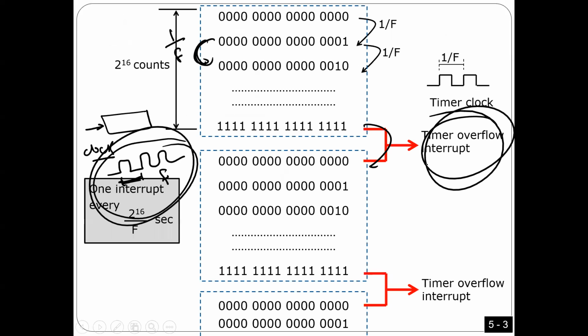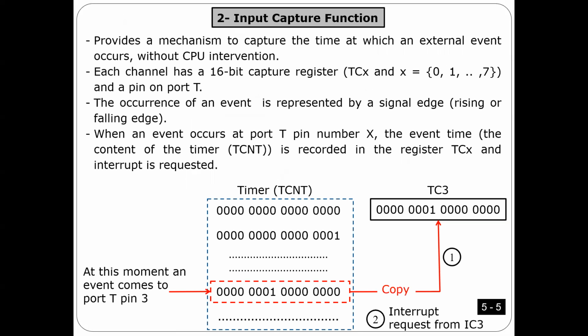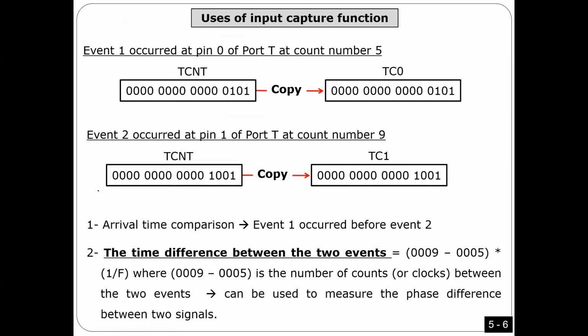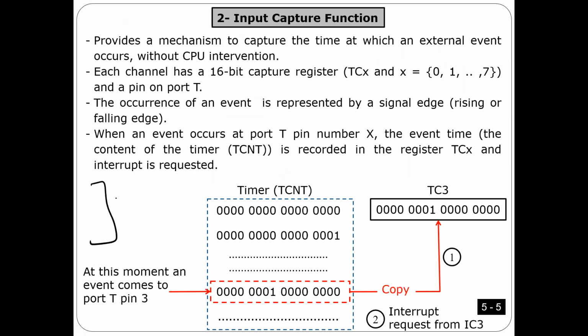Let me have a very good picture here. Yeah, look, this is how input capture works. Look here, guys. Every time there is an event on the pin, and this event can be rising, falling, or both, falling or rising. This is something you can program, similar to IRQ.